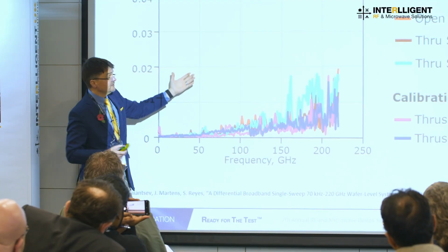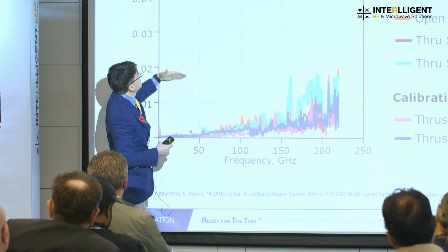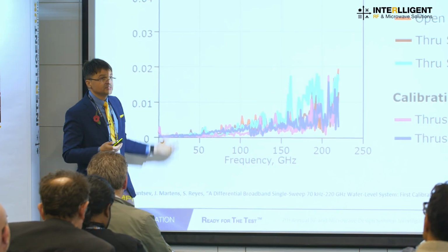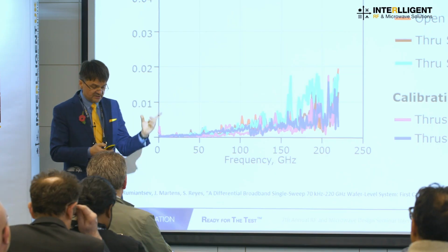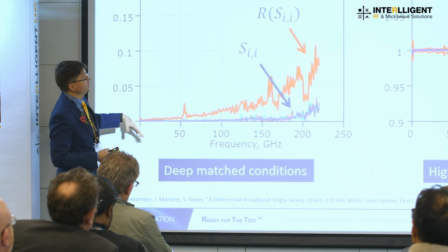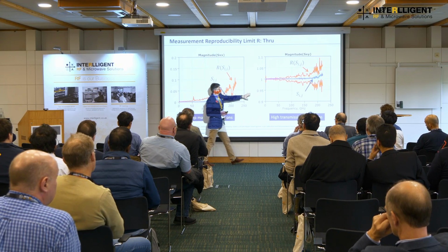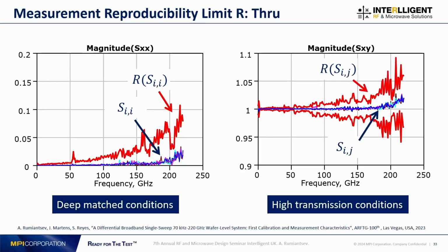And we realized that on the same setup we've got a value of measurement and calibration deviations of about 0.02. It's a linear scale, which is a relatively small number. And based on it, you can compute the confidence interval for your data. This is a linear scale, and report the measurement characteristics with the confidence interval.